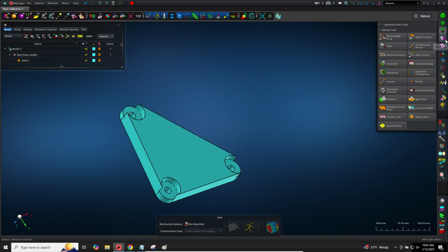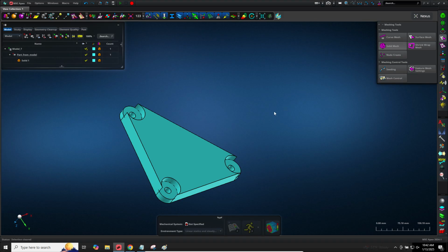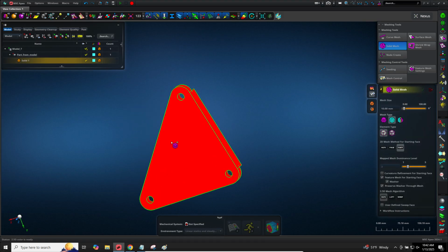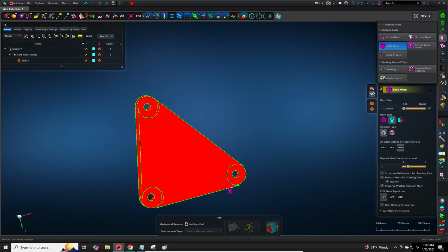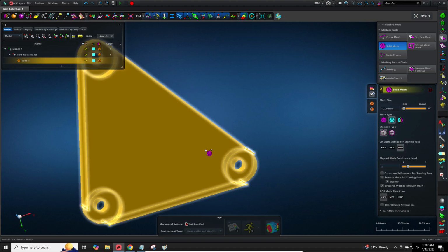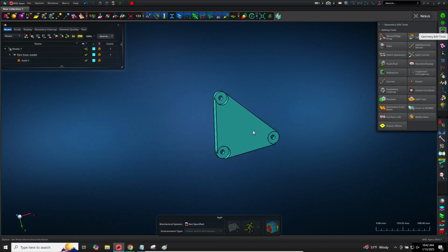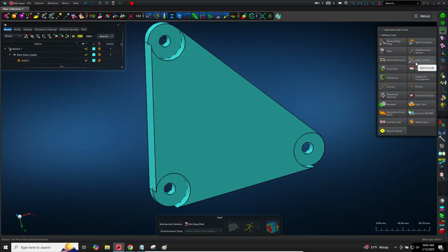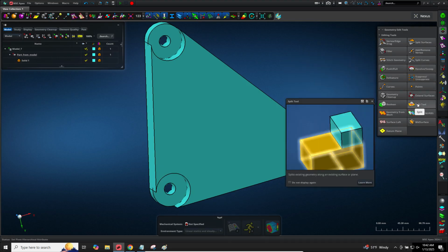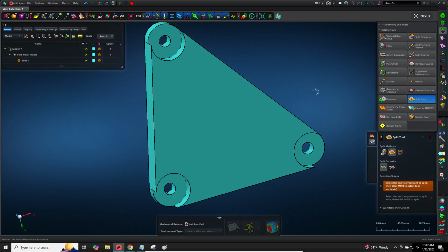So if we look at the hex meshing tool again, everything is red. One side of the face, which would be this side, is no longer similar to all the opposing faces here. So what we need to do is create what are called partitioning. So if we open the geometry tools and click the split tool, there is a partition option here.